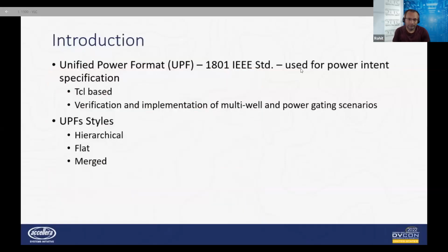The Unified Power Format, or UPF, is an IEEE standard. It was originally developed by members of Accellera and then donated to IEEE. It is a Tcl-based standard which is intended to ease the job of specifying, simulating, and verifying IC designs that have a number of power states and power islands. UPF helps reflect the power intent of a design at a relatively high level.